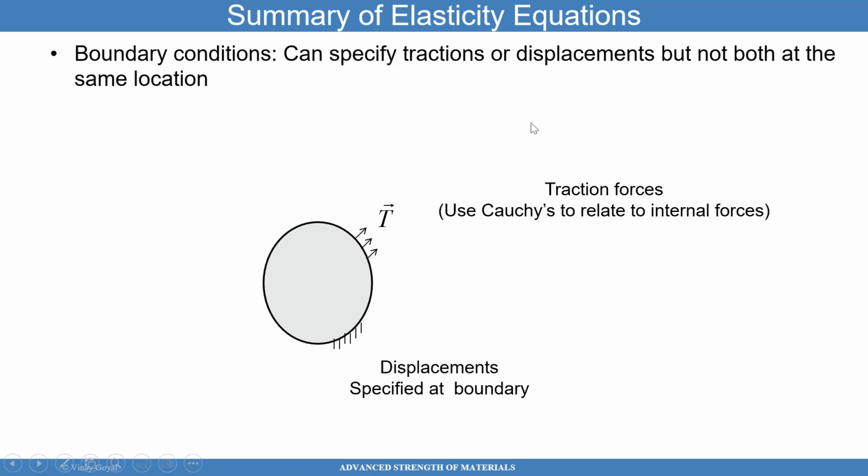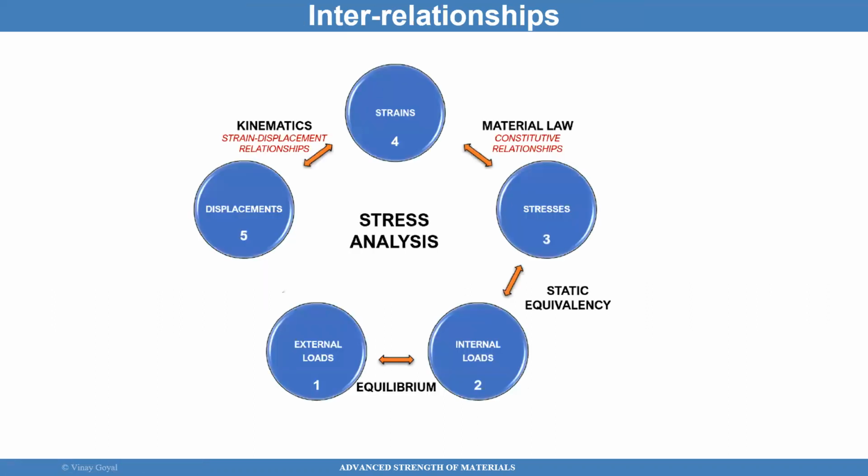Okay, so we'll continue here then. And this is more like a map to show you all the things that go into a simulation. You have external loads, you have internal loads that are really your stresses there. They're reacting to external loads applied. And the stresses are going to help you figure out where the structure is going to fail. So that's the idea there. Stresses are related to strain through the constitutive law, and strains are related to displacement through the kinematic deflections. So when you're solving problems, you're going to be using all these equations as a whole to be able to tackle certain problems.